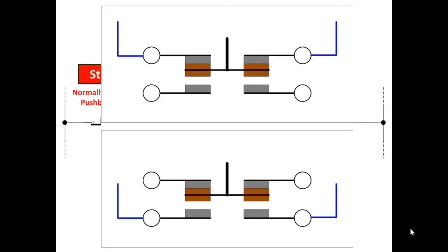Separately, you buy a contact block. And the contact block that you're looking at here, you're looking at two of them. It is the most common contact block. It has one normally open, one normally closed. The top contact is normally closed, the bottom one is normally open.